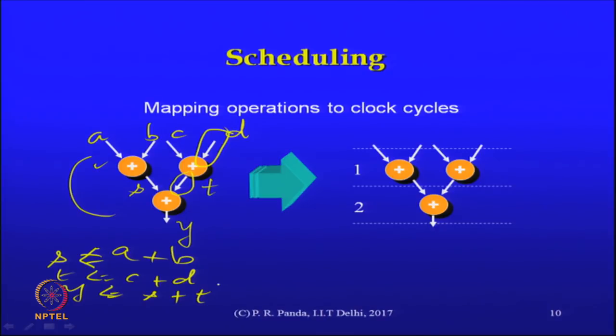Okay. But often we will skip the HDL part of it and will directly show the graph and show the operations and the algorithms that are working on the graph. But remember, they all came from an HDL that we ourselves wrote. What is scheduling then? The scheduling is taking these operations and associating a clock cycle with them, associating a timing with those operations. We did not specify any timing in these assignments, right.